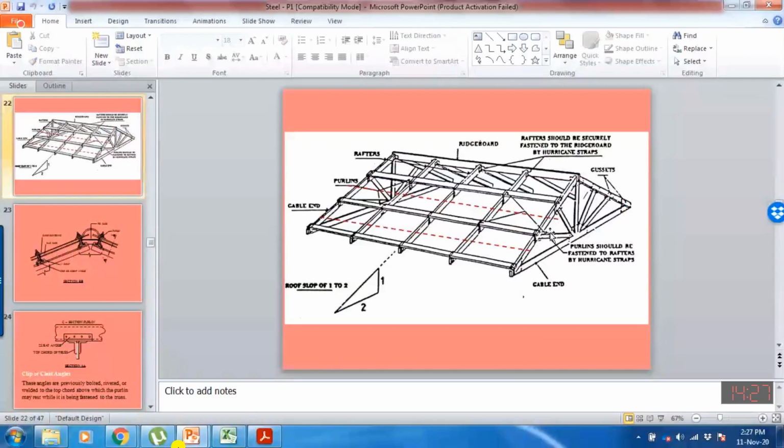But if it is bending in this lateral direction, this sag rod is controlling the bending in the lateral direction. It means that in this lateral direction we have one extra support. So in this lateral direction our purlin is a continuous beam having two spans. Ends are simply supported, and the sag rod is behaving as a roller support.